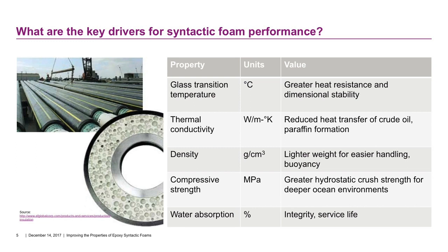Thermal conductivity, the insulative quality of these foams, inherently so because of the fact that they contain these air-filled microballoons or gas-filled microballoons. The insulative quality of these foams is going to address the heat transfer between the crude oil, the rigid pipe wall, the foam itself, and then into the surrounding ocean environment. So the transport efficiency of the crude oil is imperative. You can also address paraffin formation by controlling thermal conductivity of the formulation.